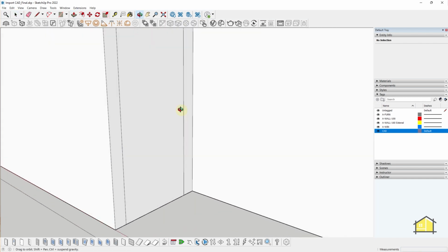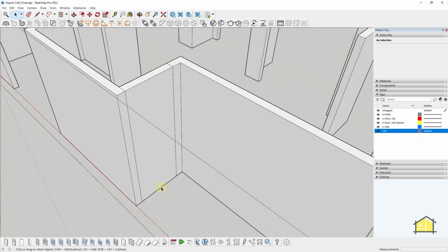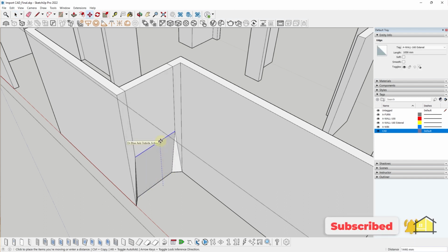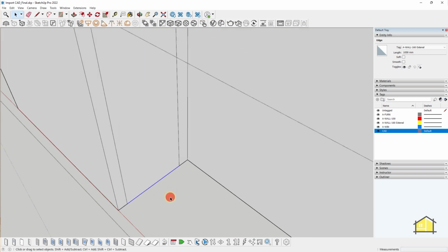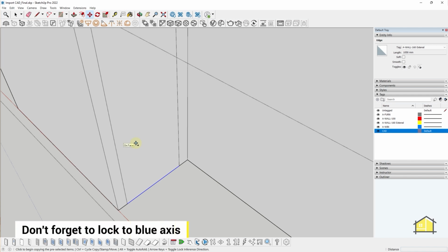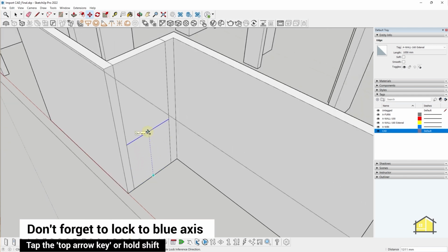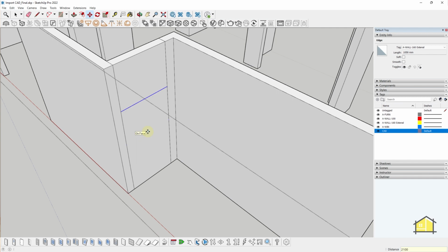Now, a lot of students, when they move this line on top, this happens, and that's because you're not making a copy of this line, but you're rather moving the line. So what you would need to do is select this line, press M, and then tap Ctrl on your keyboard. So that would toggle the copy mode. And now if you make a copy, it would copy the line. So you can copy this to 1100 mm. And we've created that line, which will also separate the faces.